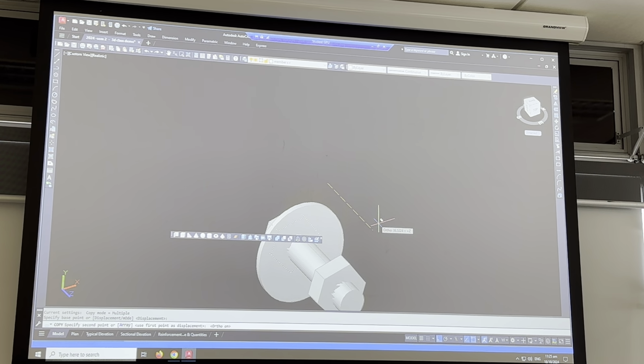So although my notes just say timber truss, you need to also call these things up. And you'll notice that in my example, there's a section that says the grade, the type, the nominal size, and the length. It's also important in the elevations to call them up as well.